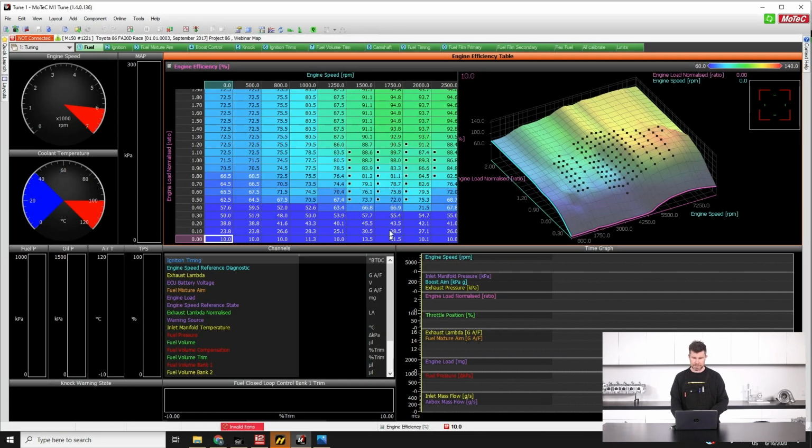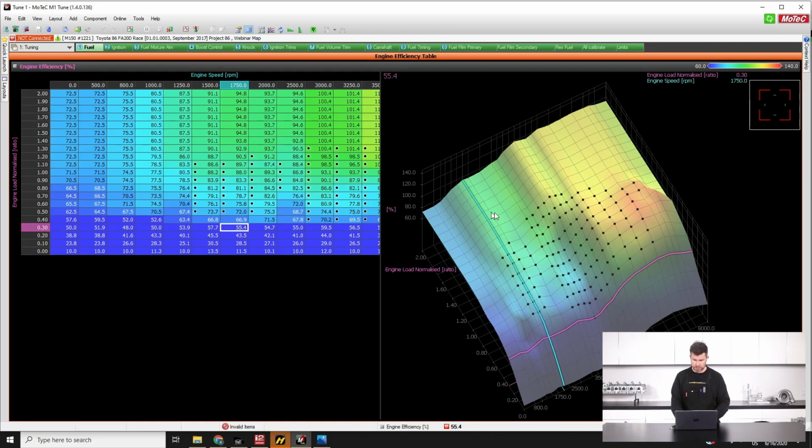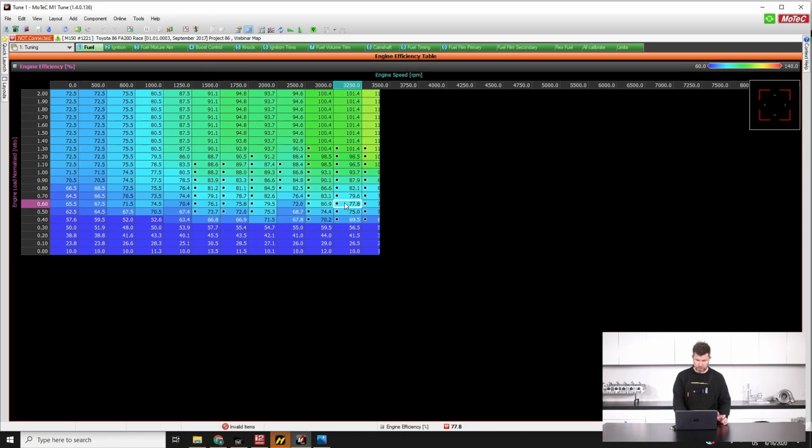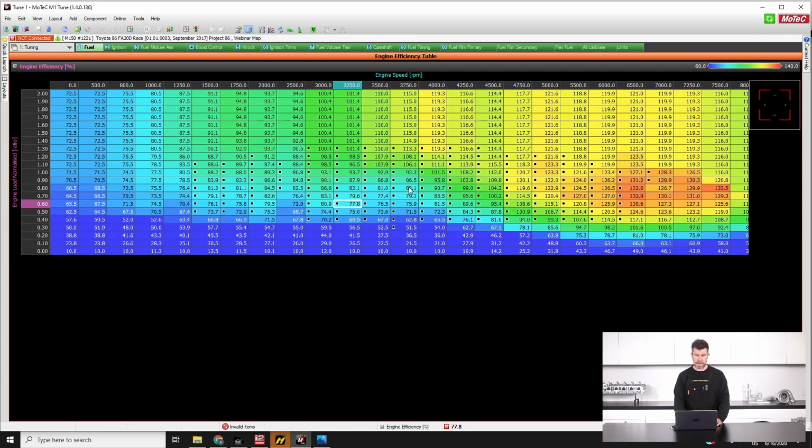And that's what happens if we come back and have a better look at our table here. So let's just full screen this, and let's actually get rid of our graphical view, and we'll go full screen on our table. So in a ramp run here, we start with a pressure ratio right about here at about 1.1. As we come up on boost, we see our pressure ratio actually peaks. I think from memory it peaks at about 1.4 at about 3,500 RPM, and then of course at higher RPM, as the exhaust pressure builds, it drops back and we end up getting down to around about 0.9.